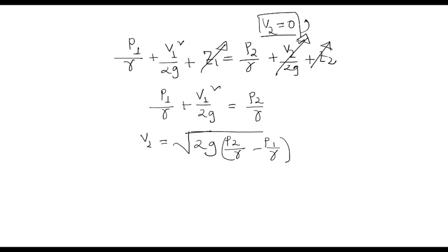In actuality, directional velocity fluctuations due to turbulence increase pitot tube readings. The fluctuations create some turbulence, so the pitot tube reading is increased. So we must multiply a factor for correct data, which varies from 0.98 to 0.995.